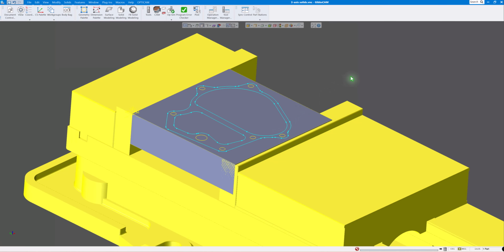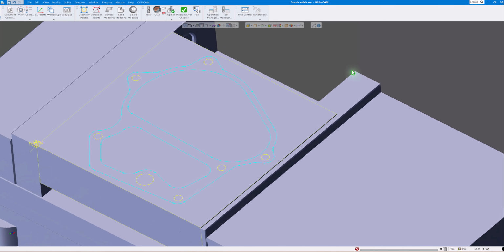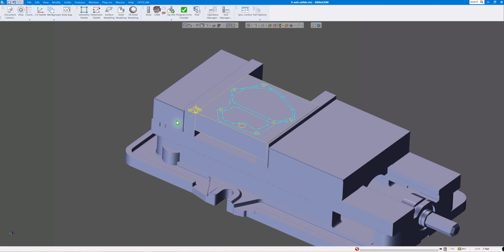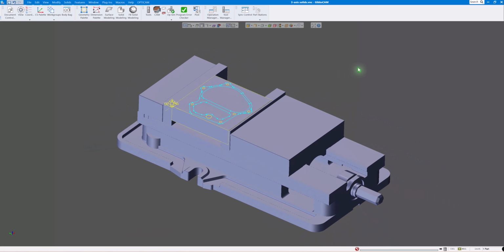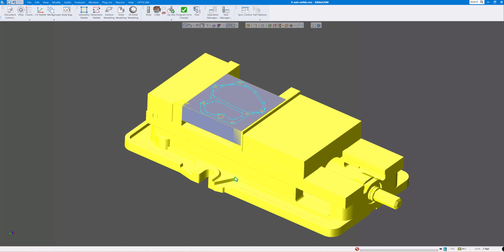And it's going to bring in our vise. And of course you can see the origin on the vise matches the origin on our part. So we need to change our course vise into a fixture. So make sure face selection is off, select the rear jaws and the main vise there.